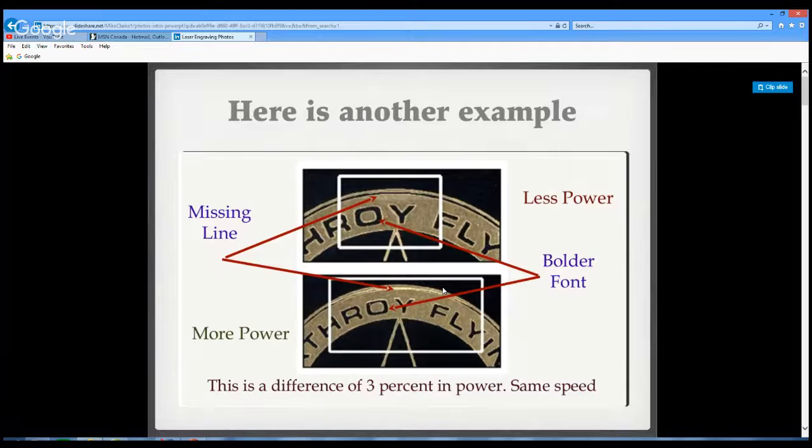But normally what I'll typically do, and it's brought up in the slide presentation here of how to actually adjust, is I create a rectangle, and I start laser engraving the rectangle, and I try to get a good looking rectangle with the least amount of power that I can get away with. So I may send something over with 100 speed and 30 power, and then I may do something with 20 power. I may do another rectangle with 10 power. On most machines, we can adjust the power on the fly.